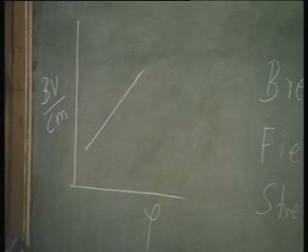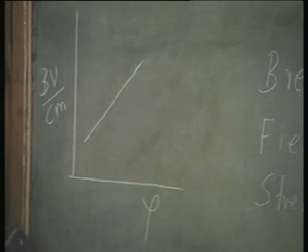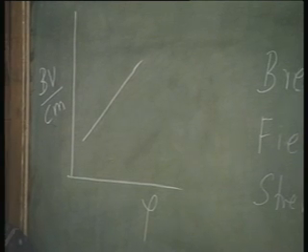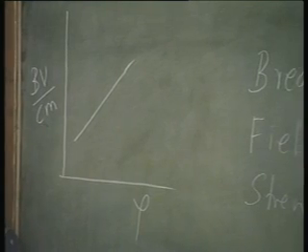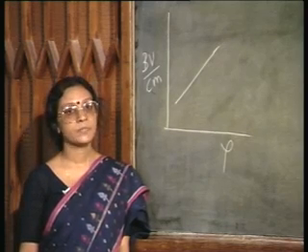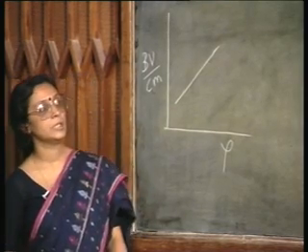So, therefore, since dry thermal oxidation gives the most dense oxide, one gets the highest breakdown field strength using the dry oxide. So, this is what we mean when we say that dry oxide quality is much better. This is one of the things we mean.